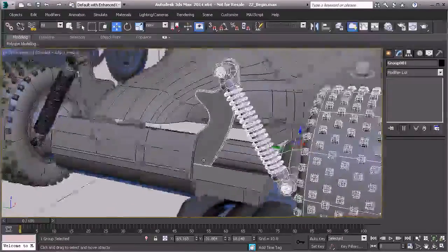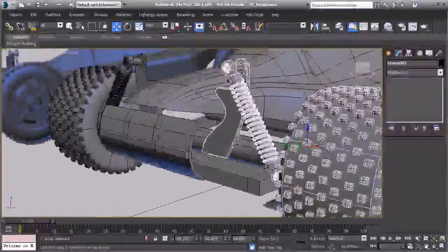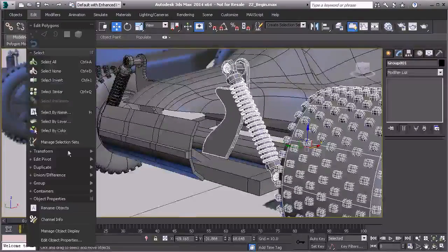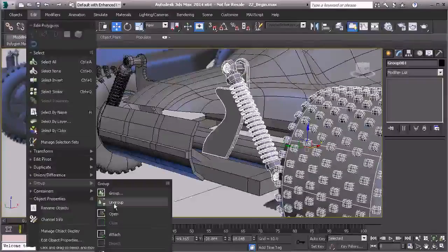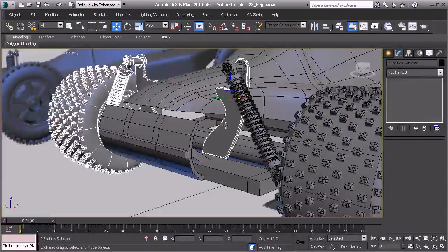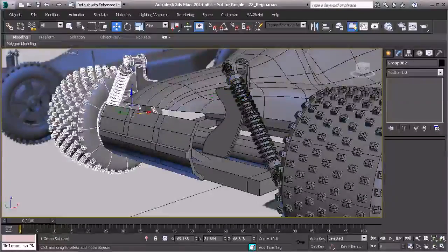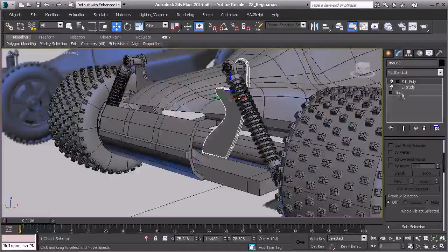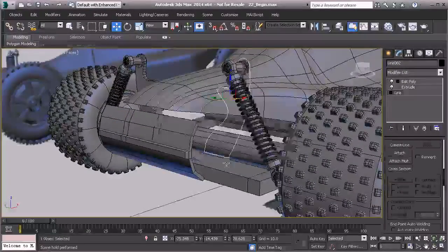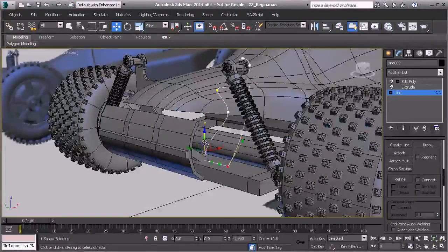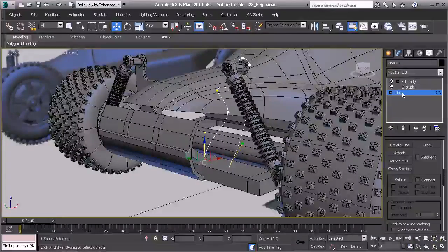And also another thing that I just noticed was the connector pieces here. You might want to take the lower part of that and just lower that down. So you'll have to go to Edit and Group, and let's ungroup that. Let's see if we can just select that one piece there. And we'll have to do that on the other side as well. So Edit, Group, Ungroup, and let's go to Line. We're going to hold Yes, and I'm going to take that set of vertices right there across the bottom. Just pull that straight down to where it intersects with the frame.